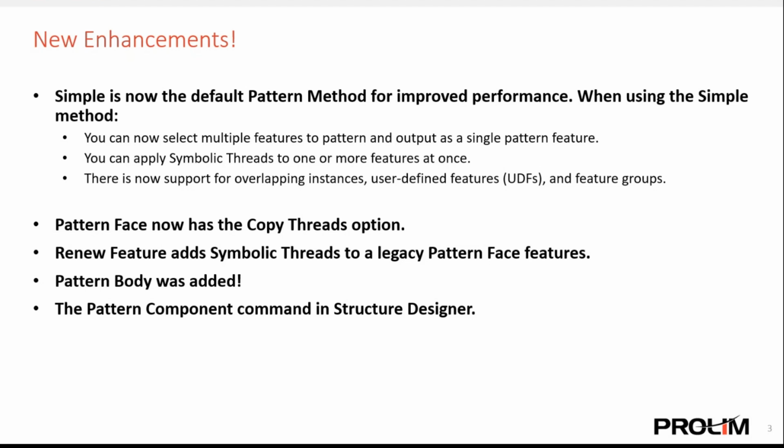In the pattern geometry, the renew feature now updates legacy pattern geometry features to the current NX version, and any feature changes are reflected in the renewed feature as well. Editing of a legacy feature utilizes the legacy UI, and the feature is updated in that version as well.